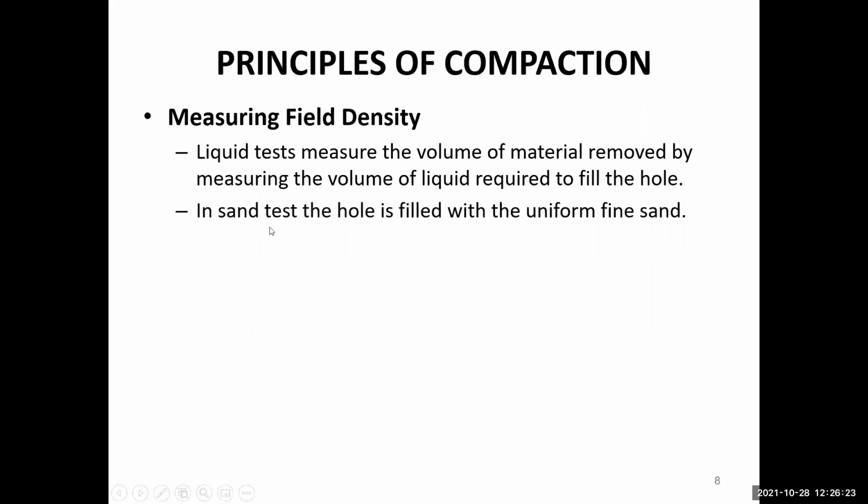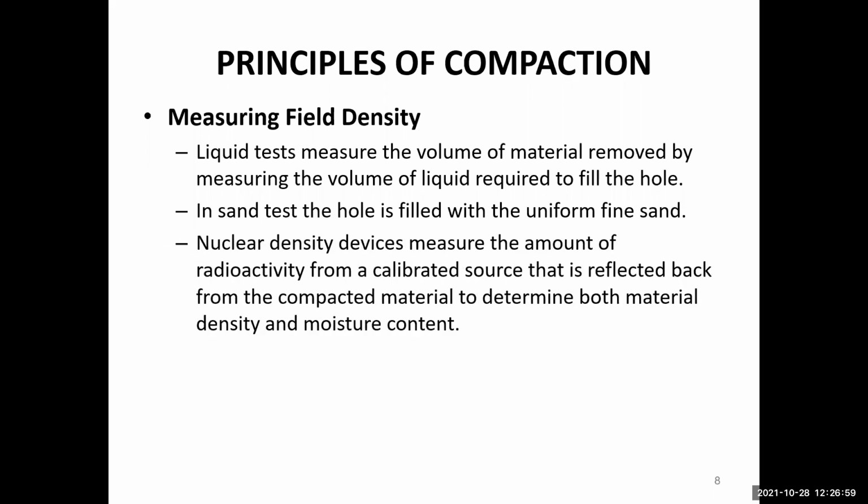Similarly, in the sand test, the hole is filled with uniform fine sand. If the soil is such that it may absorb that liquid, or the liquid may not be readily available, or it is difficult to measure the weight of the liquid, or there is some difficulty when the liquid test cannot be performed, the hole can be filled with sand instead, and then we can measure it with the uniform sand, with the density of the uniform fine sand as well.